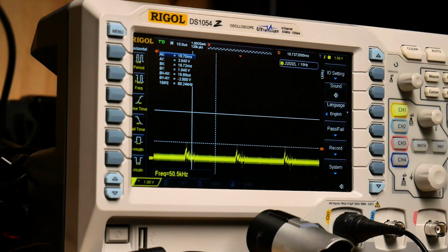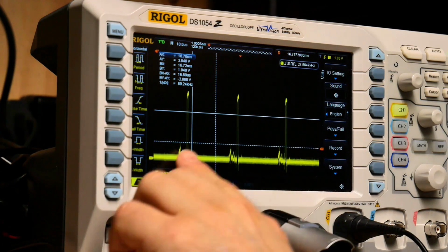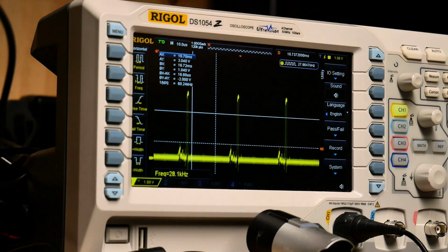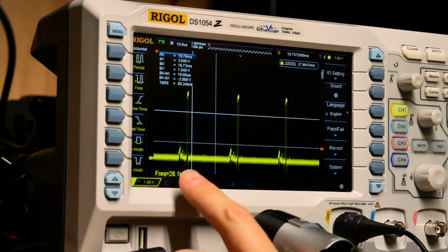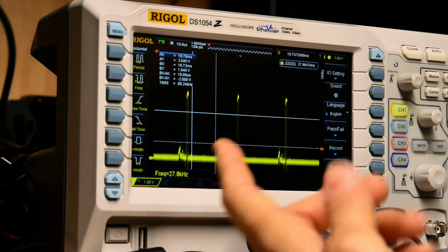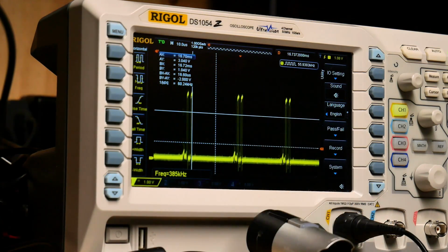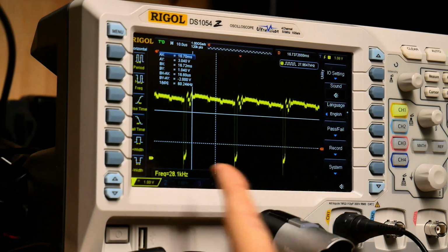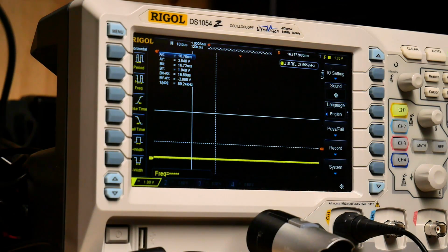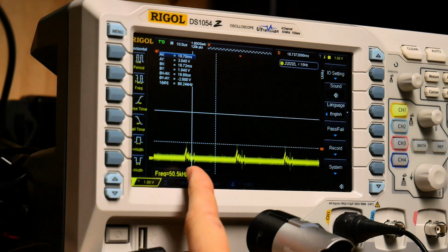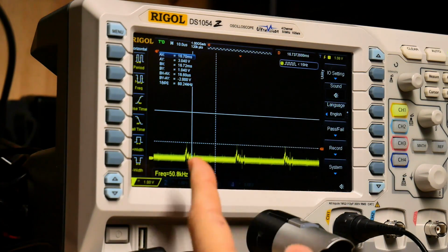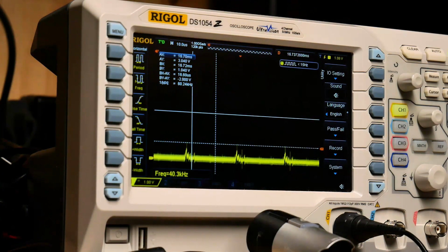Okay, data line 0 is screwed up. It's held low. And we're getting pulses there, so that's okay. Although notice it has a little bit of screwed upness there, so maybe that's normal, I don't know. So that looks really good. That looks like a good signal. That looks good as well. That's good. That is not good. That's just like it was before with the other VDP. It's sort of just stuck low and stuck low.